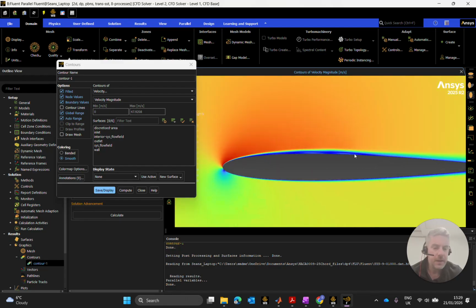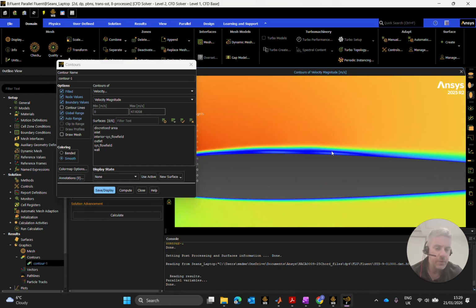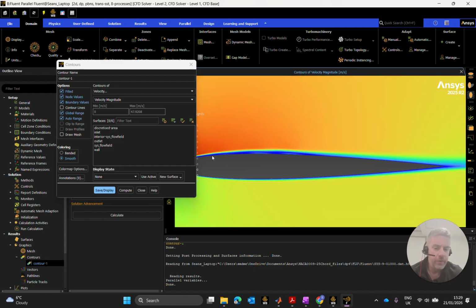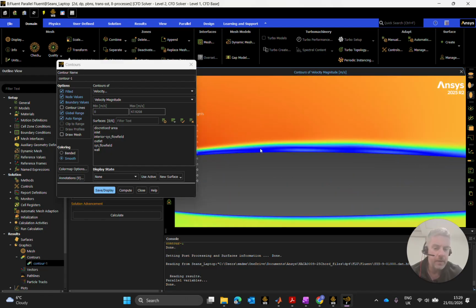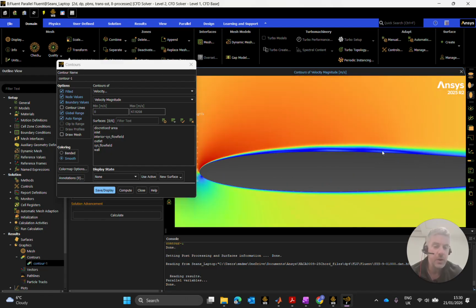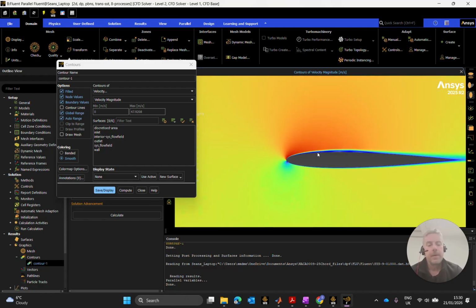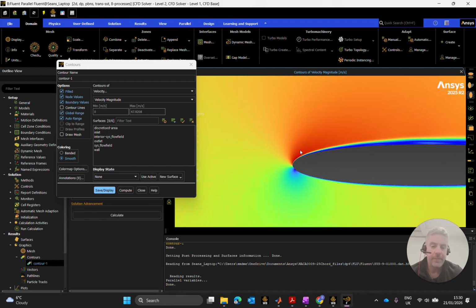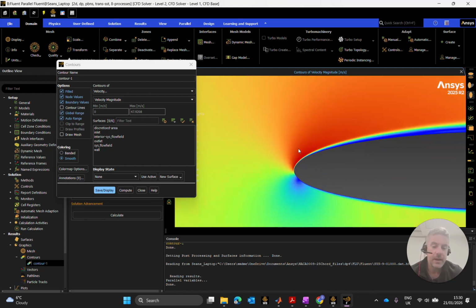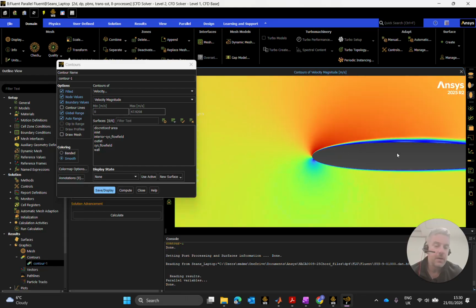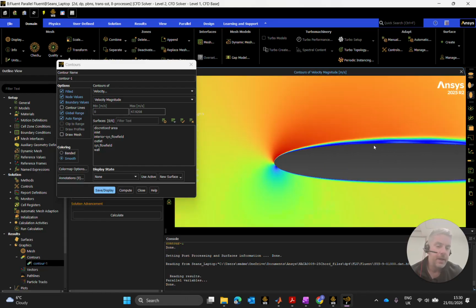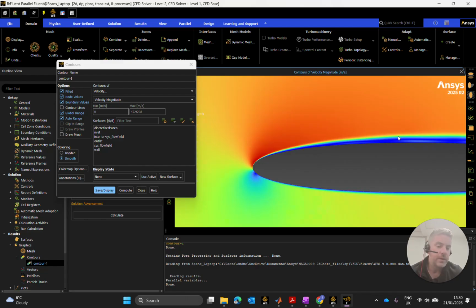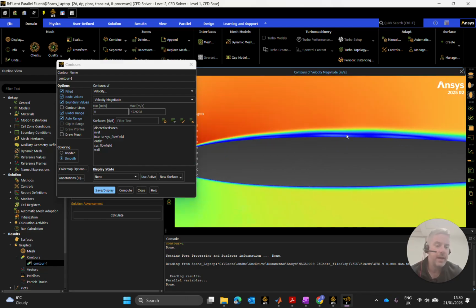And so it seems there that you can see the blue region, the low speed region, has gone up quite far, where we are looking to accelerate flows over the front. The very leading edge here has a very high gradient of velocity coming over that, but then it dies off fairly quickly with this particular airfoil, and there we are.